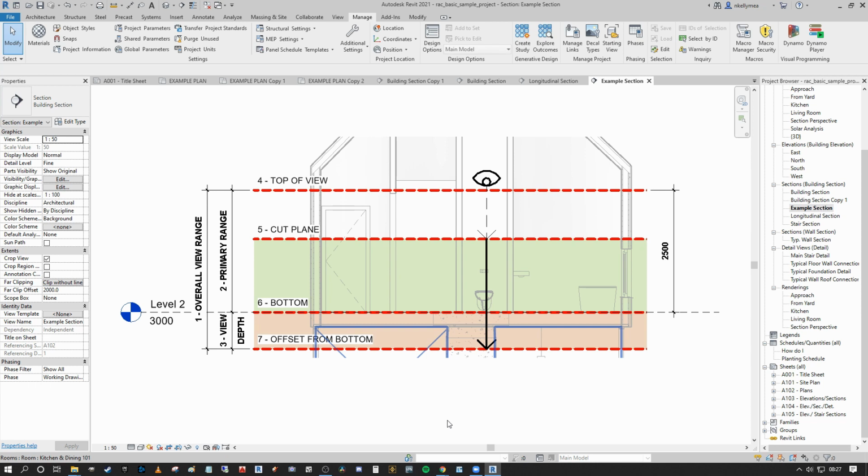They will present with their default projection and cut line styles even in this view depth here until the point that this extends beyond about 1200 mil. I think it's 1220 millimeters or 4 feet. Once you go beyond that, then it will take on the beyond line style, but they have a different default property where they'll present as normal because they're typically below the view range anyway, and therefore you may want them to show with their default projection and cut lines accordingly.